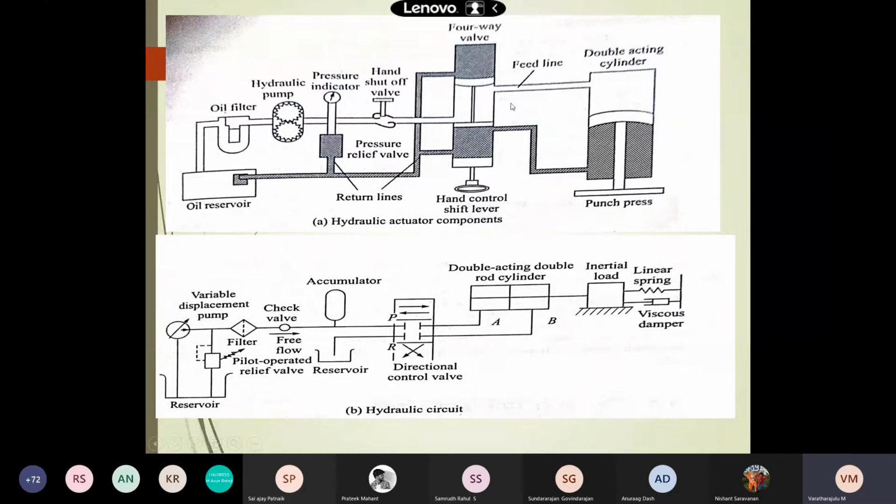The teeth of the gears have a perfect meshing, and that serves both to transmit the drive and to maintain a seal between the suction and the discharge side. And we need to take care of this system, because oil trapped between the successive lines of contact does not build up pressure, and therefore we need to be very conscious when we are handling this hydraulic system.